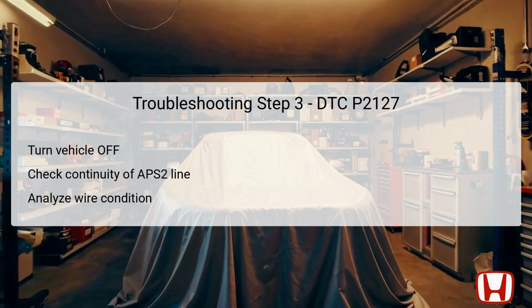Ensure that any continuity between test points 1 and 2 is checked, where test point 1 is at APP sensor connector number 3, and test point 2 is to body ground.